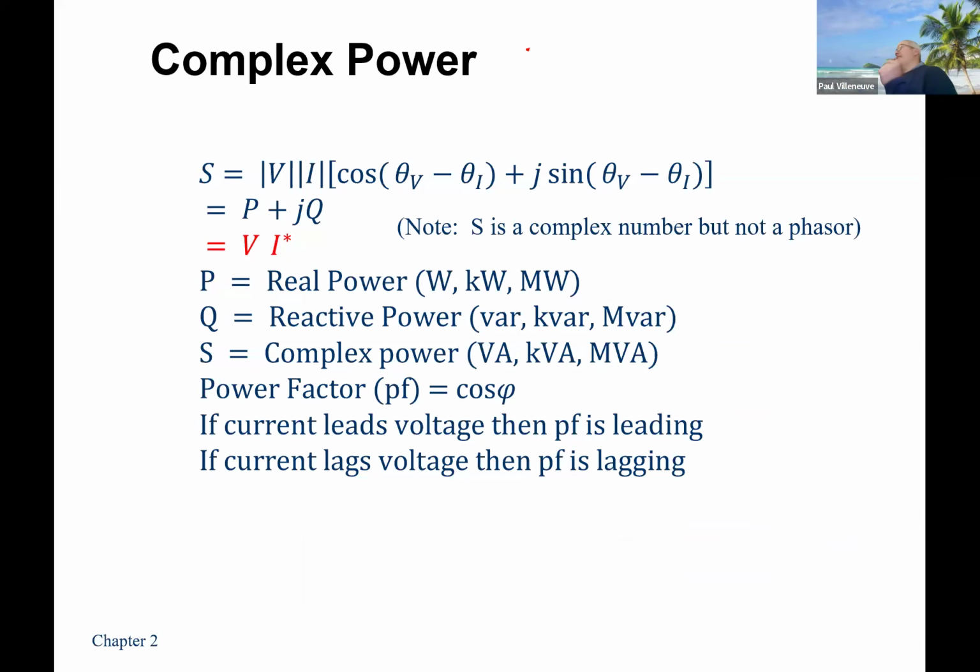But essentially what it does is, depending on the phase shift, you will have some negative power that has to go back to the system. So if the phase shift is 0, if there is no phase shift between voltage and current, what type of load would you expect it to have? Purely resistive, right? And how much power is being stored in a resistor? None, right? It's all being dissipated. There's no fields that you can store it in. So all the power that goes to the resistor is dissipated. None has to come back.